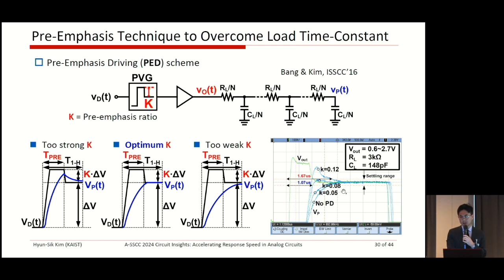Okay, so without any pre-emphasis driving, the response must follow the time constant limitation of the RC, right? And with the pre-emphasis technique, a more sharpened and very fast output response can be achieved.